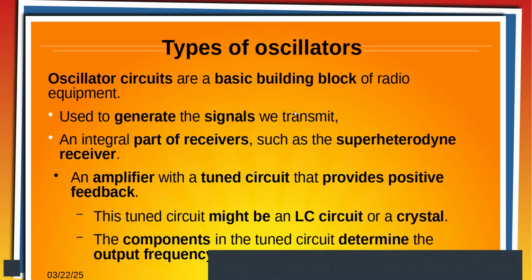So essentially, an oscillator is an amplifier with a frequency dependent feedback circuit that has enough phase change to make it a positive feedback. It turns out it's not easy to build a working oscillator, as I've learned.